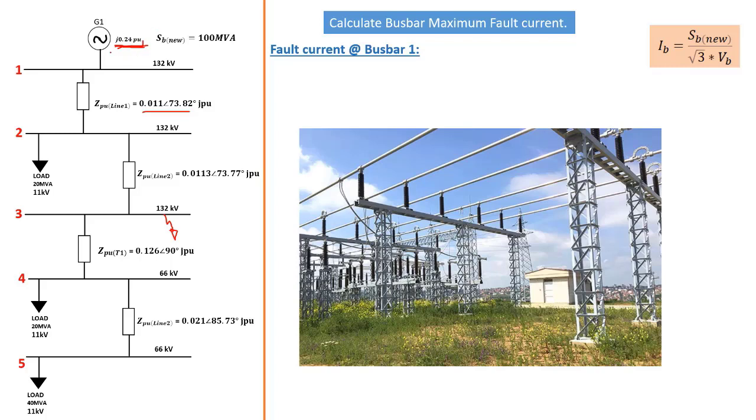Now this internal resistance determines what is the maximum power that the device can deliver. So in electronics design, for instance, if you are designing a power supply, you have to make sure that the overall impedance of your supply is low so that there is maximum power transfer.